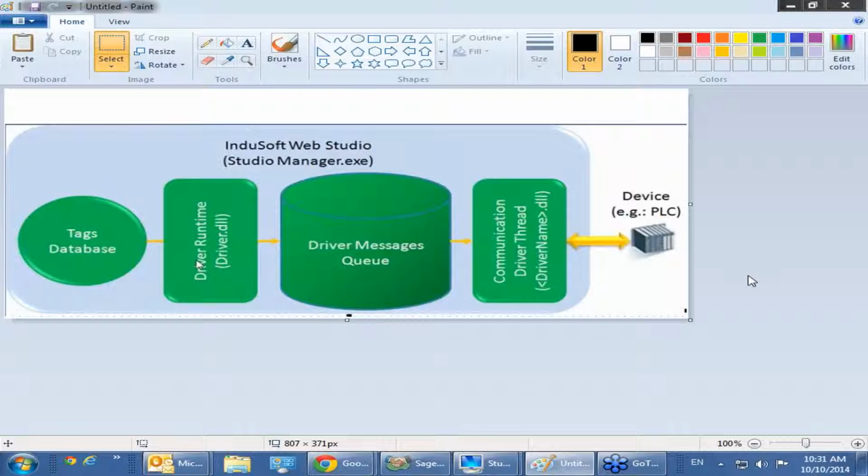I think I understand his question. I think he thinks the ZT2551 is a Modbus slave device. It is not a slave device. The ZT2551 connects with Modbus RTU slaves via the RS-485 bus. The individual slaves will have their own specific address, but the ZT2551 doesn't have a specific Modbus address. It is just a means of communicating to the slave devices connected to the RS-485 bus. Does that answer your question, Tom?